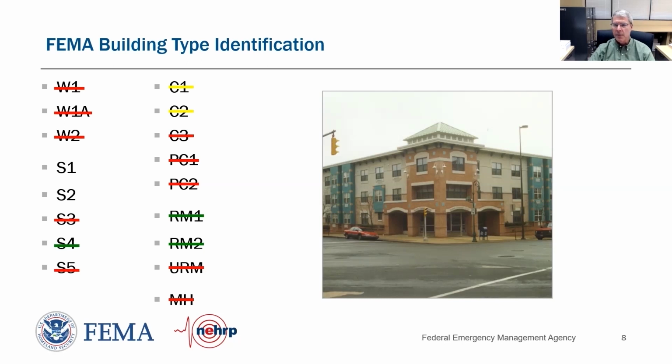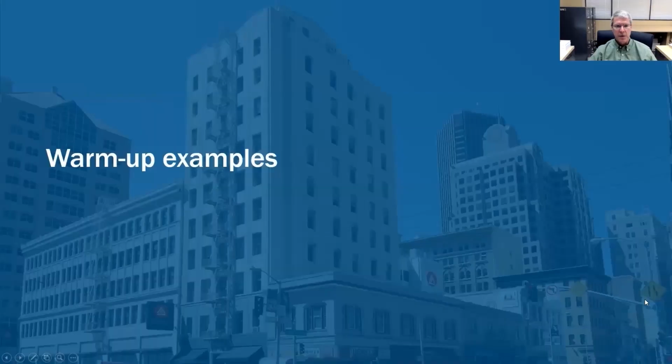So we can actually run both columns and score both. I'd be real tempted to take a peek inside the lobby down there and see if there's any evidence of a brace or not. But barring being able to look inside, it's hard to tell whether it would be a moment frame S1 or brace frame S2. And so we can easily run those two quickly.